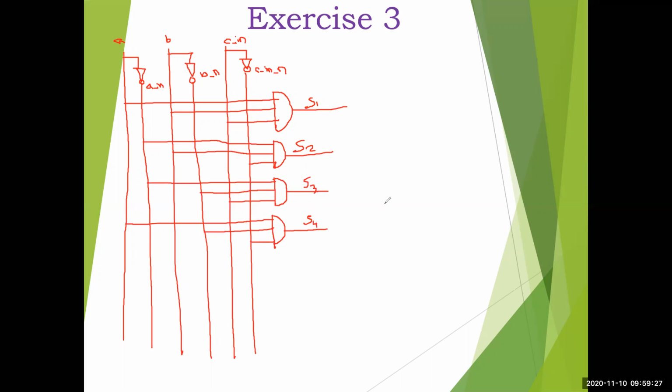In the question they have also told you can use a maximum 4 input primitive gate. So I have 4 outputs now. These are the inputs to the OR gate. So we will connect them to an OR gate. Try to make it neat. Now we'll draw an OR gate, and the OR gate output is now the actual sum of the full adder. So this is the design.